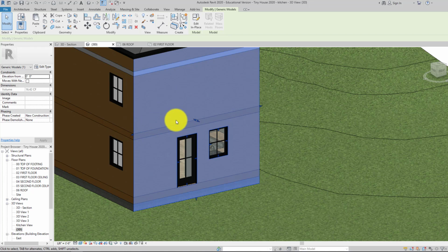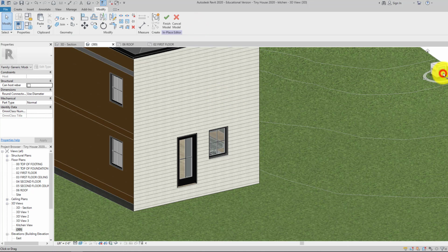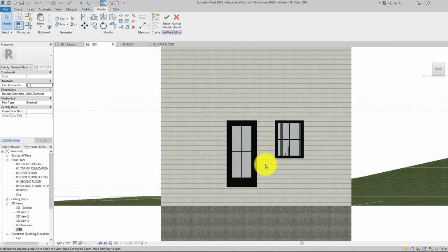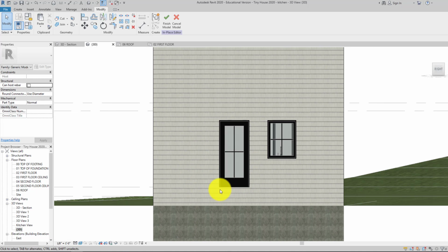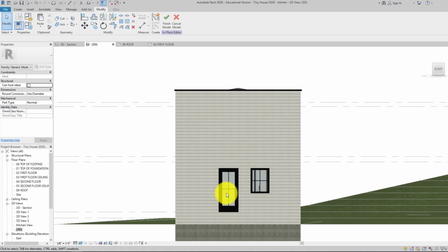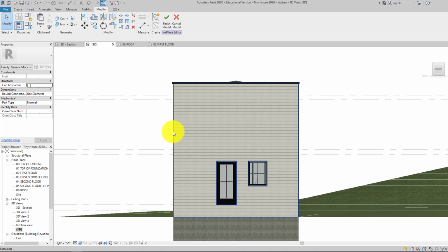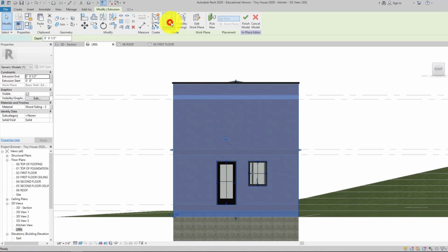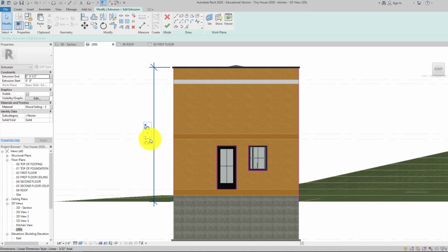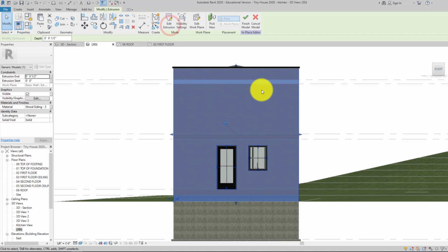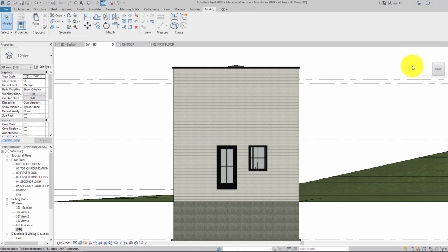So, for instance, on this side, we need to make sure that the sides are the exact same. So what I did was I did edit in place, and then on your own you can pull it down. I cut this out so it's underneath, even though it probably wouldn't be how it really is, but you can click on this and say edit extrusion, and right here we need this number right here, 21.5. So remember that on the side view when we make the other one.